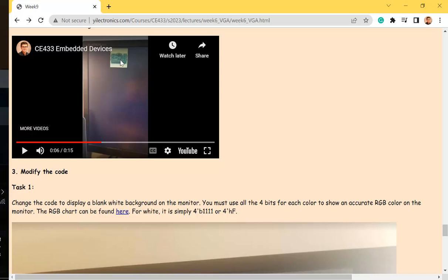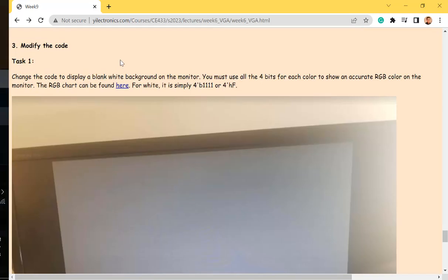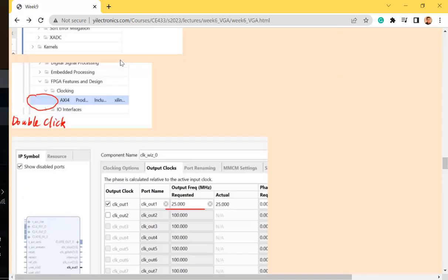And you got an image, you can take a picture of it and convert it into the data file. So the data file has all the pixel data as 8-bit data in the file. And then you load it to the memory when you program it. So the ROM memory will contain that data file, which is the image file in binary form. And then if you look at the Verilog,